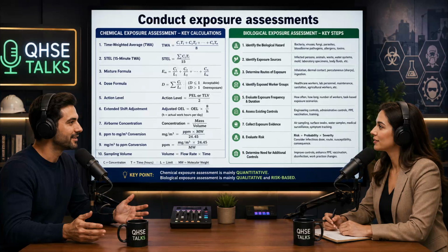But the real world rarely isolates one hazard metric at a time, you know. Very true. What happens when a process triggers both TWA and STEL concerns simultaneously? That's where it gets tricky. The sources outline a scenario for trichloroethylene degreasing. The worker pulls freshly degreased metal parts out of a hot vat first thing in the morning. For those first 15 minutes, the exposure is intense, like 25 ppm.